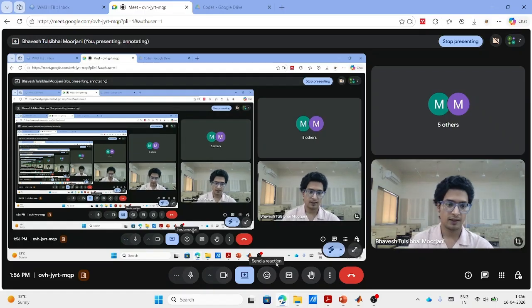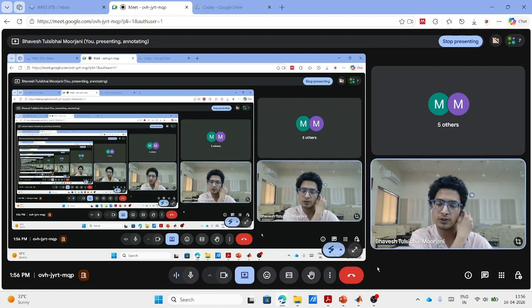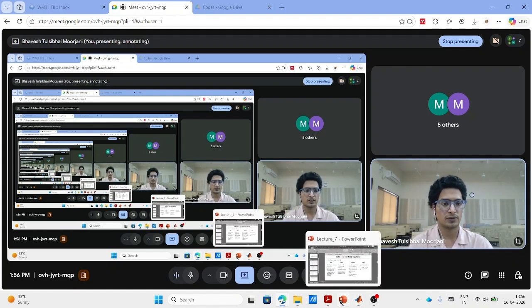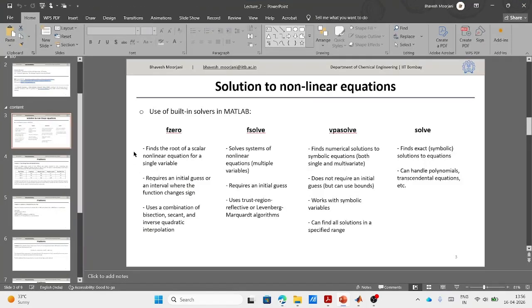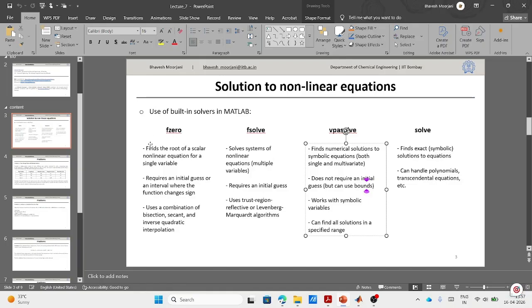Yeah, hello. So those of you who have just joined, what we were discussing was the solution to this non-linear set of equations through MATLAB, right? And if you have seen the video for the last class lecture, the inbuilt MATLAB solvers that we have are fzero, fsolve, vpasolve, and solve command, right? So where fzero and fsolve are the numerical solvers for single variable and multivariable. vpasolve and solve work with the symbolic equations, where vpasolve gives you the result as a numerical value, while solve gives you the exact solution, right?